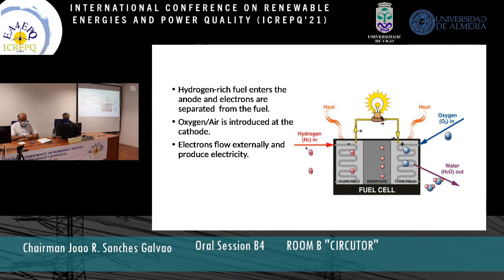So hydrogen molecules come in here in the presence of a catalyst, which is usually platinum. They break down into protons and electrons. The electrons move through wires, some type of a load, which is a light bulb perhaps, or an electric motor powering a vehicle, and they show up on the right side. The protons pass through the membrane, assuming that we have sufficient humidity. And on the right side, the electrons and protons combine into water.